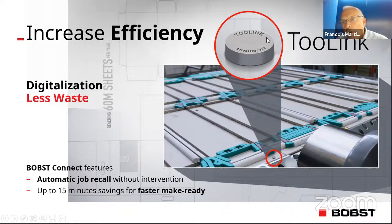Like the technology called tooling, it's very new. So you have a special chip on the tools, and it will automatically set up the machines. And by doing that, you will only need 15 minutes to have the make ready. And this is extremely important to reduce time, but also to reduce waste, because the setup is more precise.